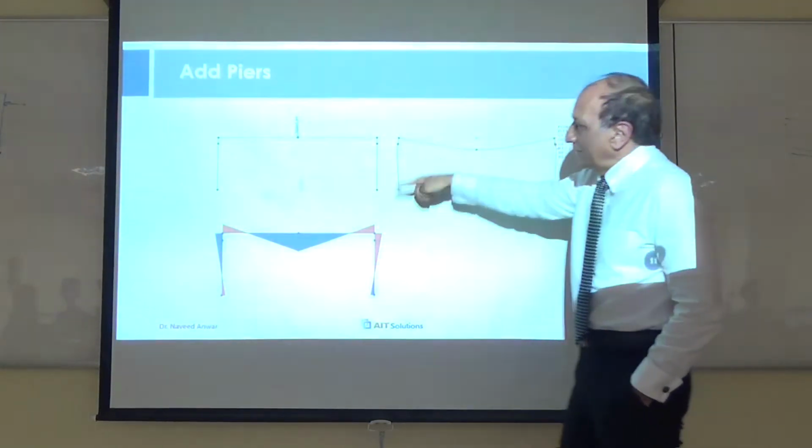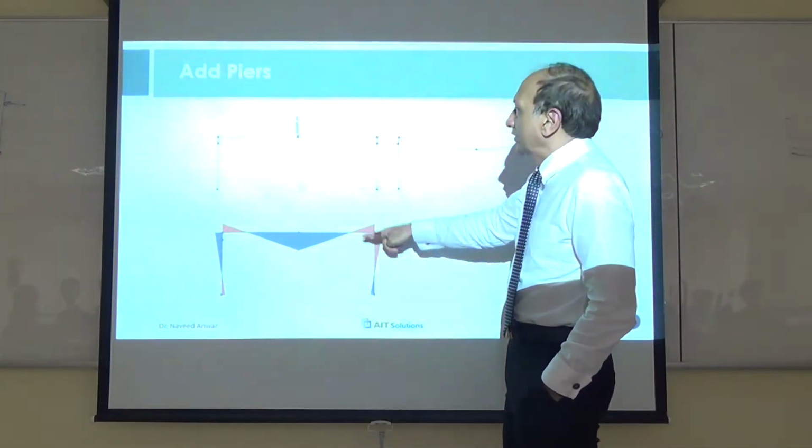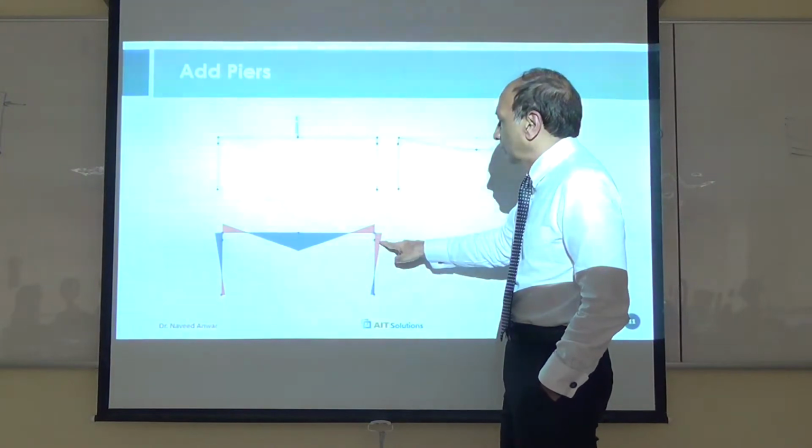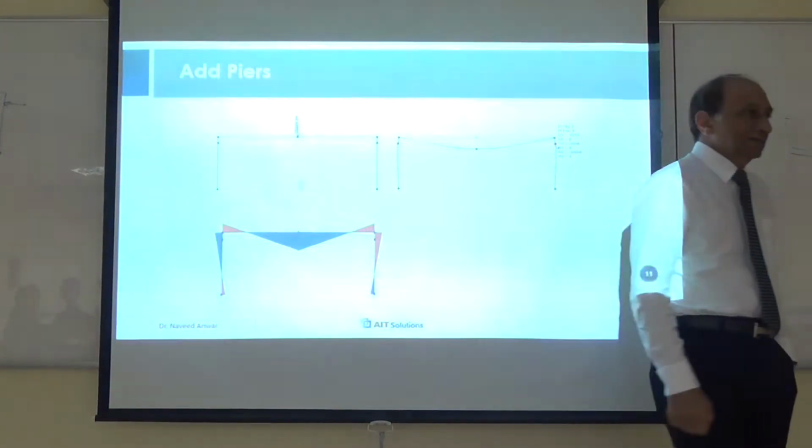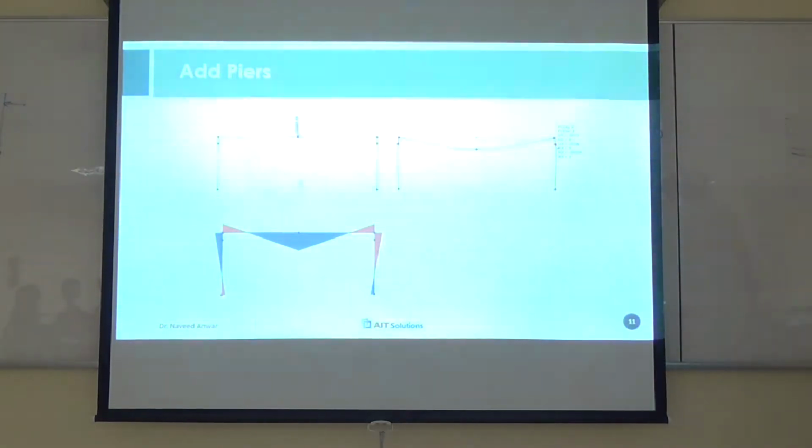And now if you apply this frame here, you will get negative moment, but that is not correct. This is for a building which is fully connected. It's not fully connected. The girder cannot transfer the bending moment to the piers because there is no moment connection there. There is no reinforcement going through there. So this is actually incorrect.